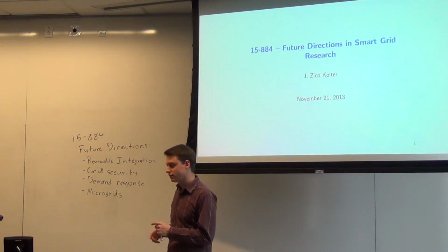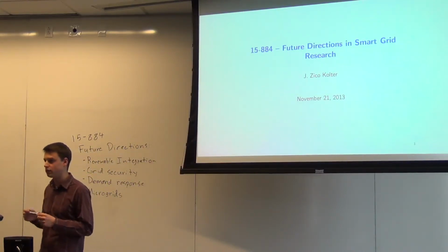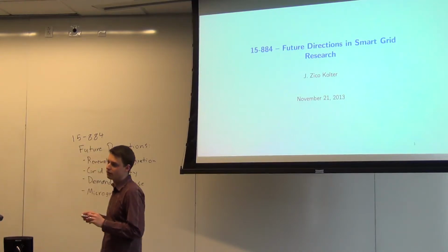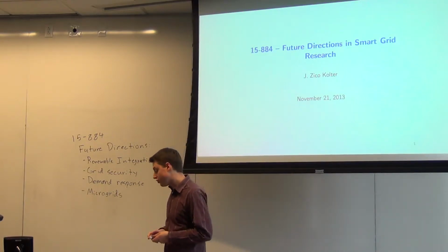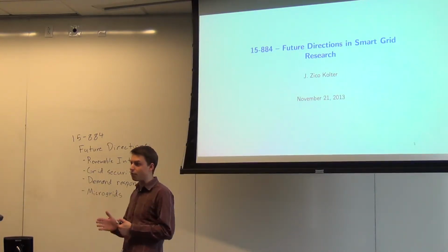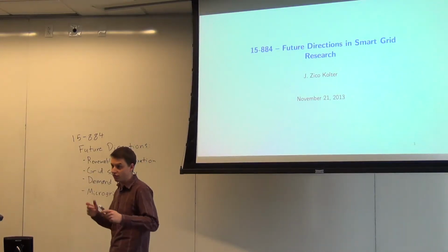Yeah? When we are doing some of the control problems, for the reference generator, is that usually or always the slack generator? Or is it kind of arbitrary? I'm a little unsure what you mean by the reference generator. Like the angular velocity. Oh, so omega ref is a fixed number. It actually is not based on any generator. Omega ref is always 60 hertz.